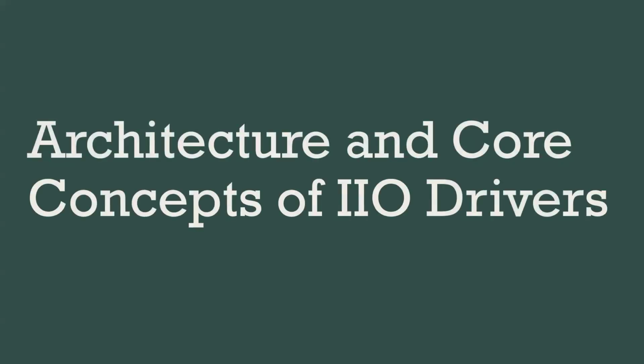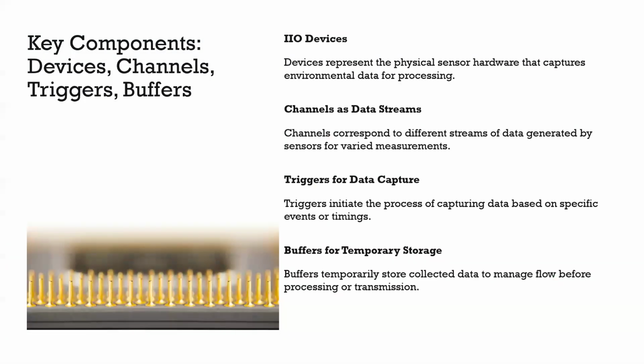Now we'll be discussing the architecture and the core concepts of the IIO drivers, the key components of IIO. As we discussed in the previous slide, the device basically represents the physical sensor hardware that captures the environmental data for processing.